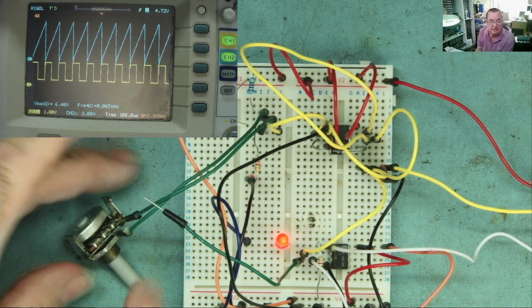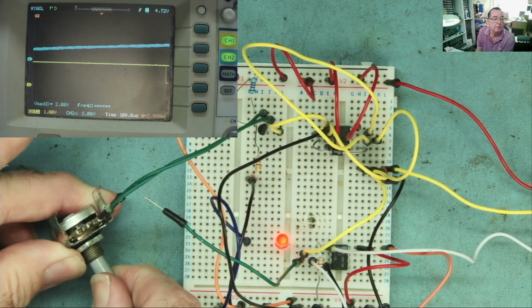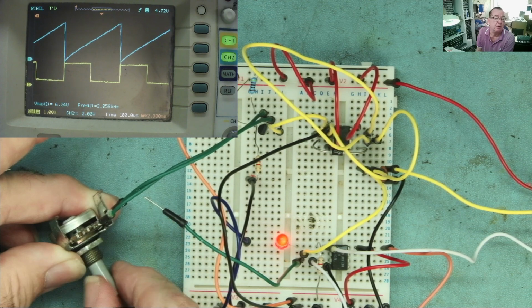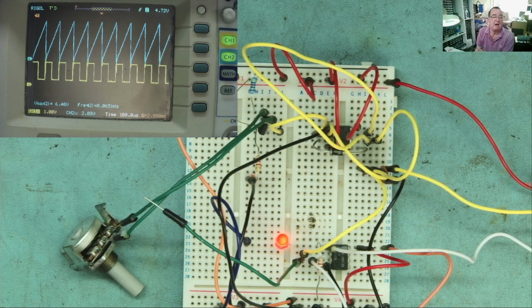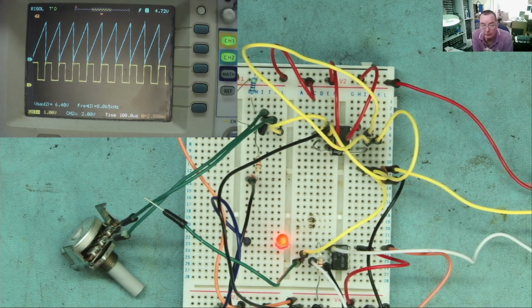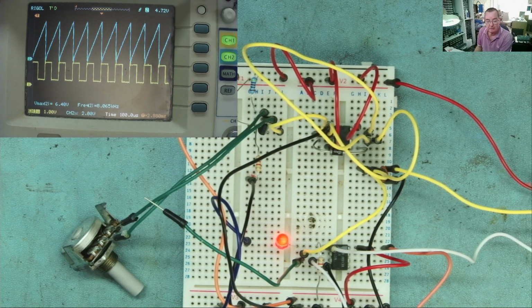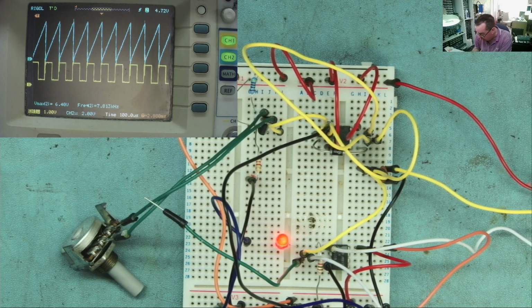And if I alter the frequency here, wait a second, change the frequency of the oscillator. Okay, I can make it slower. That's the maximum with the components I'm using, so that's a 100 nanofarad timing capacitor and a 470 ohm resistor. Okay, so that's giving me around 8 kilohertz. The other potentiometer here, this is adjusting the reference voltage on pin 3 of my comparator.